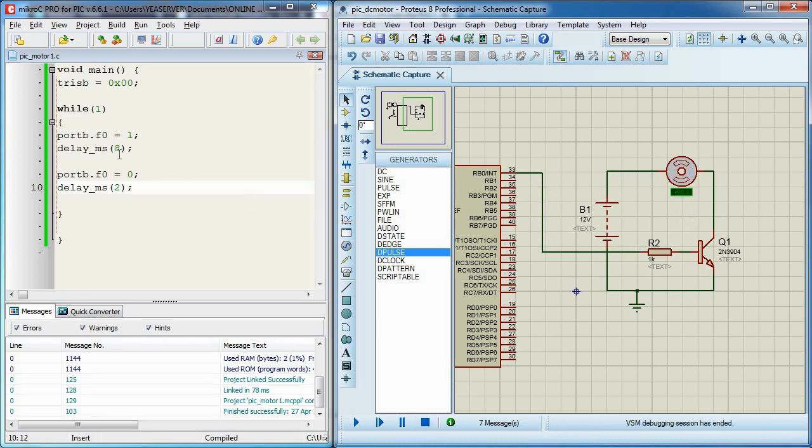And now let's change it to 20% only. The motor rotates but very slow, and the maximum speed is about maybe 15 only. So that's how you control the speed of the DC motor using PWM signal and a transistor. Okay.